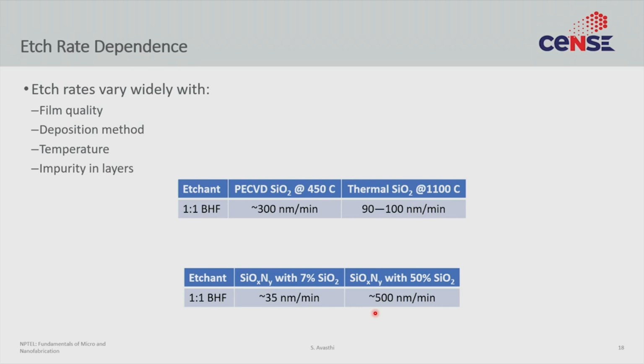So you have to be a little careful when you are talking about wet etching. In fact, this variability and this lack of controllability is what led people to move towards dry etching in semiconductor fabrication, because dry etching just tends to be a little more reproducible.